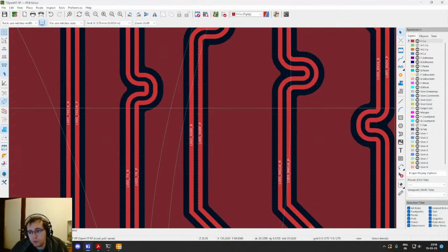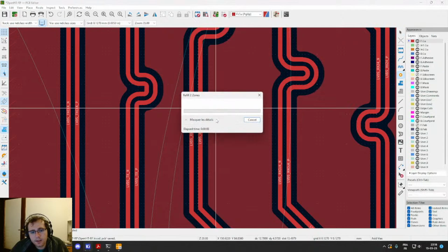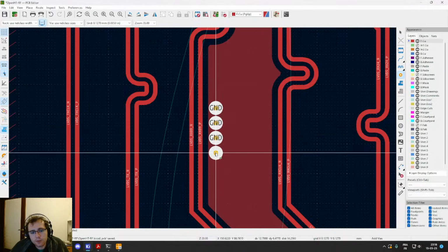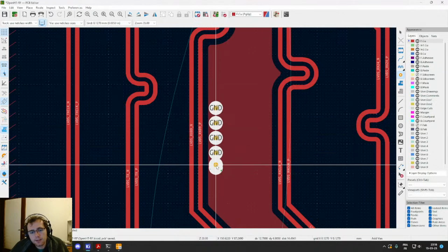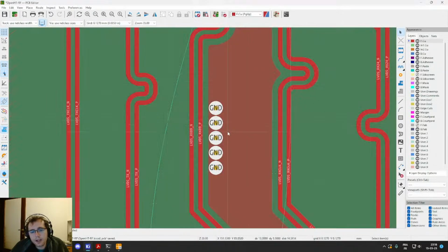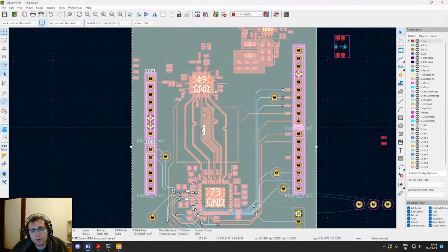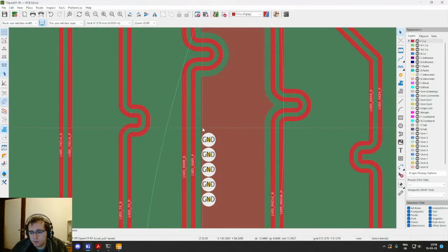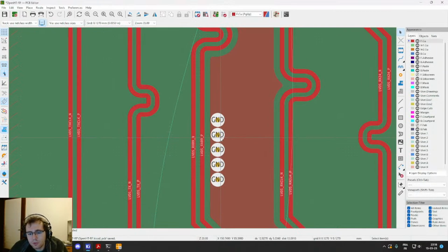And so what you do is you take vias and you place them like this around your tracks. Then you have on the second layer this whole green field. It's ground, your reference ground, what you call 0 volts, but the world doesn't care what you call 0 volts, but it is what you call 0 volts.